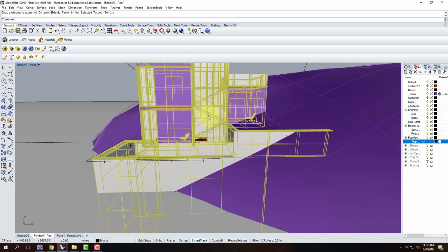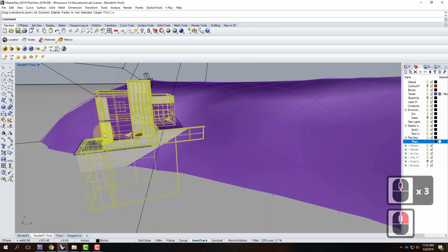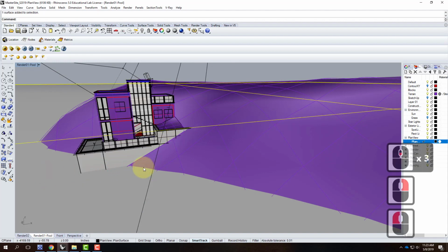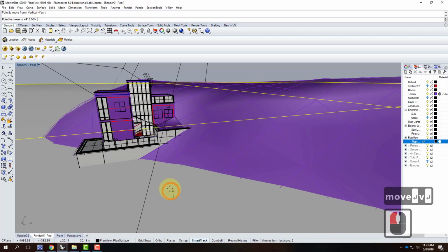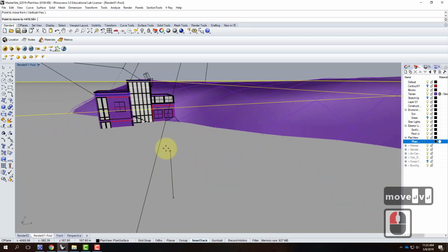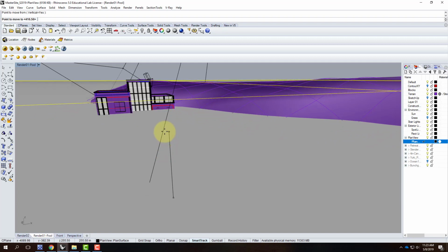Usually you pick 4 feet above wherever the floor plane is, and that's where you cut it. But since this has multiple floors, I want to make sure that I'm cutting it appropriately. Alternatively, I could cut it at the top here and cut through the top of this room, one way or the other. So I can do it in a less precise manner by just moving this plane, V for vertical, and I can just move this plane up to the point at which it's cutting through my building at the appropriate place.